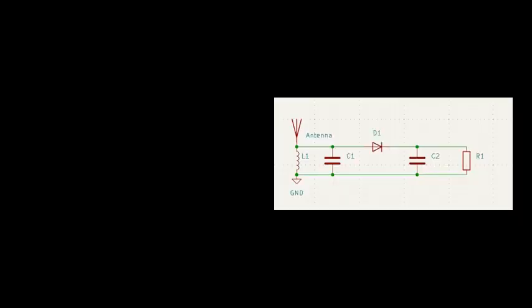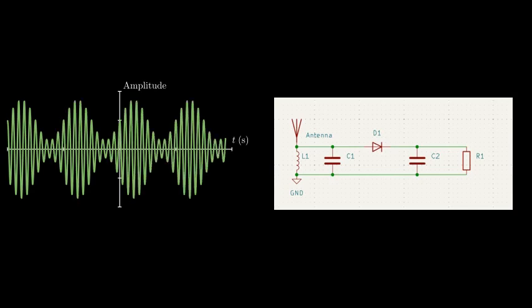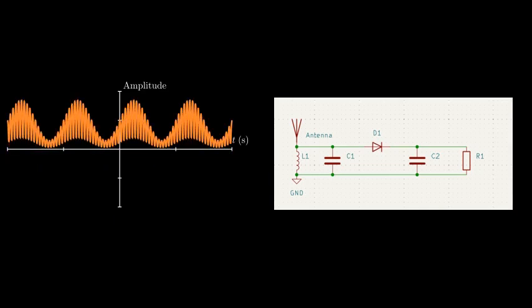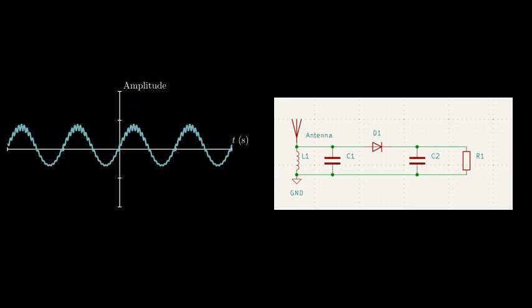So now I'm going to explain the AM receiver component. So first we have an antenna leading into an LC bandpass filter, and the way this works is by thinking that inductors only allow lower frequencies to go through them, and capacitors allow higher frequencies to go through them, so we can tune it to only allow a certain frequency to pass through the circuit and all other frequencies go to ground. And then we have a diode to rectify the desired signal we have in the circuit now, and after that rectification we can filter out any of the carrier signal and get our audio signal.